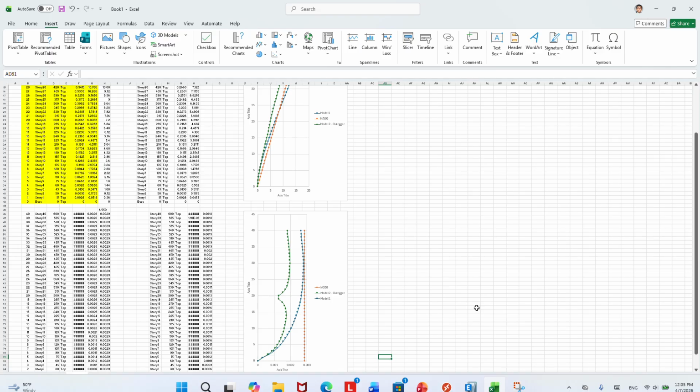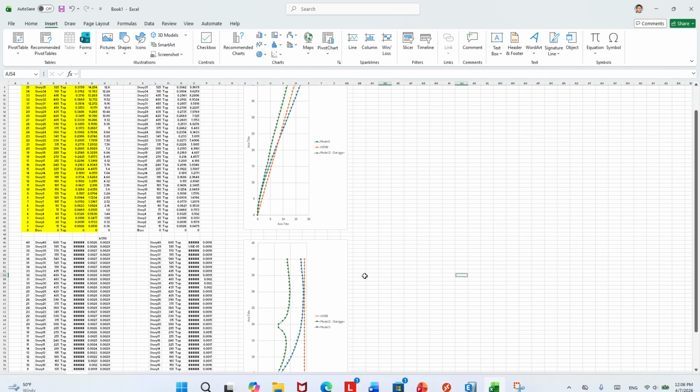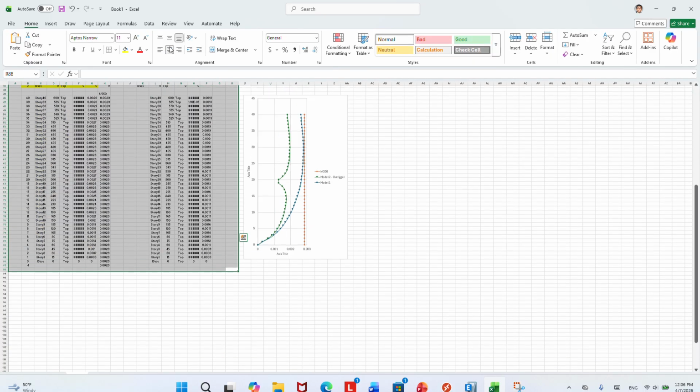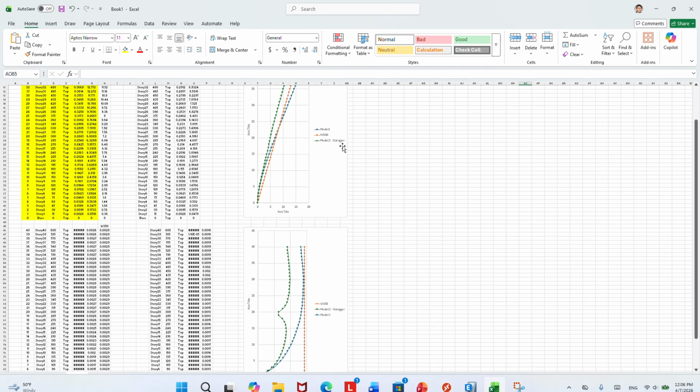So basically, this is an example. I mean, the system we limited to is the core wall, coupled shear wall with outrigger. The reason why I want you to play with it, I think it's 90% of all high-rise buildings, they adopt this system, the outrigger system with a concrete shear wall system. And some unique projects sometimes adopt something new, but this is more common, and that's why I want you to kind of adopt this. So far, any question?